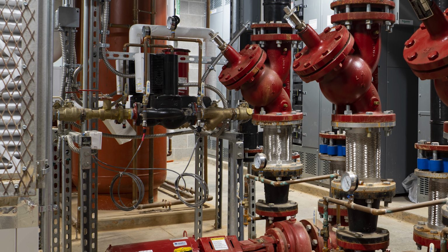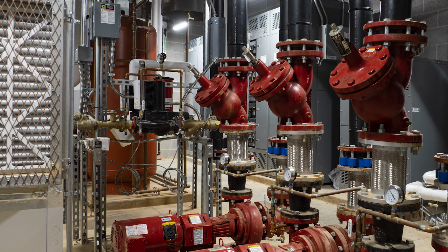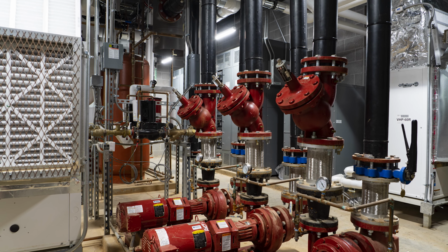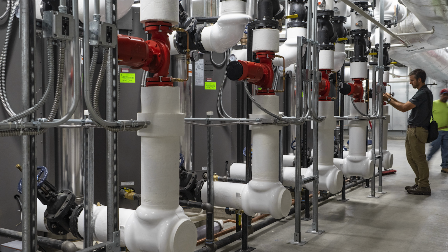And finally, we've really moved past commissioning into optimizing a building and its performance. So our group of engineers will get into a room, will trend a building, see how it comes out of morning warm-up, see how the building is functioning, and look for those opportunities to enhance the operation well beyond what you could do in a standard typical commissioning setup. So building optimization may be the number one feature in getting a building to truly perform. When all of these processes come together, then you can really achieve drastic energy reduction.